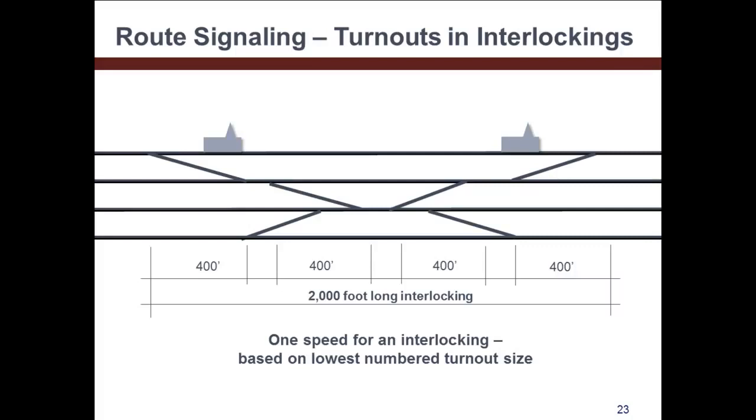Well, as you know, for an interlocking, the dispatcher controls the switching and therefore the track that the train will take. The train engineer obviously anticipates the route, but not the exact track that will be used where and when he is running. So only one speed limit is indicated in the employee's timetable for each interlocking because there's no simple way in the timetable to provide the speed limits for all the turnout possibilities?